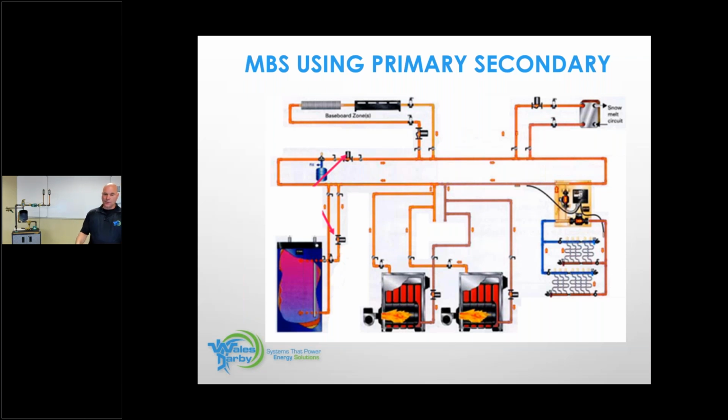The reason we're doing this in this type of system, this is a multiple boiler hot circuit, and then we're teeing off with closely spaced tees for primary, secondary. So this circulator is not seen by the boiler circulators because of this hydraulic separation point. This circulator is not seen by that circulator because of this hydraulic separation point, and so on and so on. Okay, everybody's good?